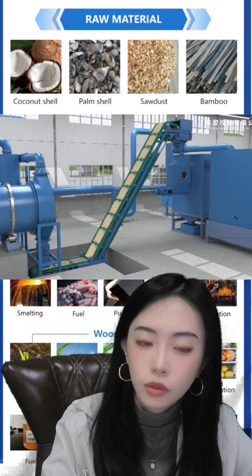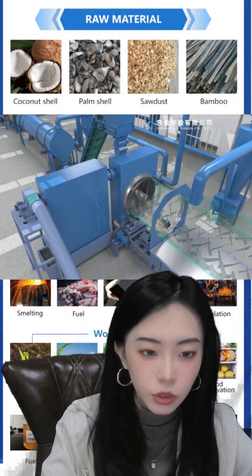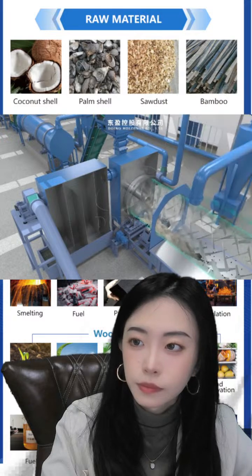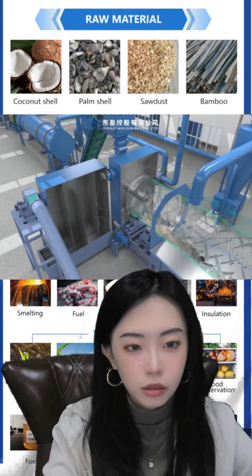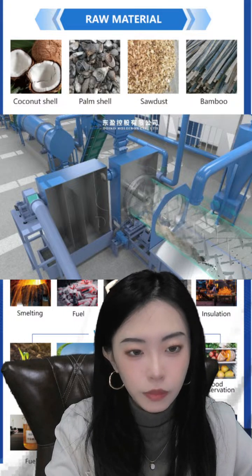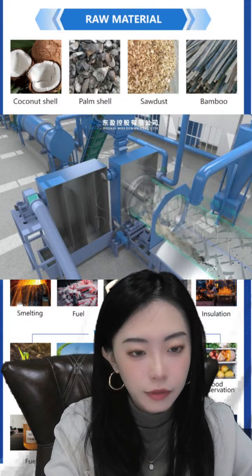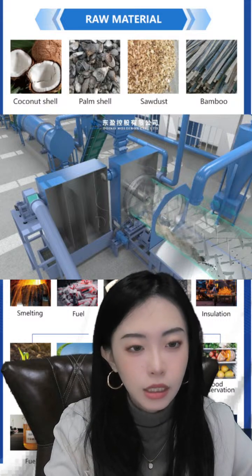And then the material goes by conveyor to the carbonisation system. You can see here the carbonisation system, it will control the moisture. If your material's moisture is higher than 15%, we need a second dryer.